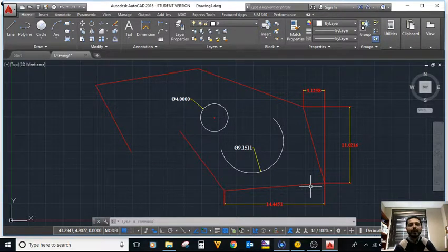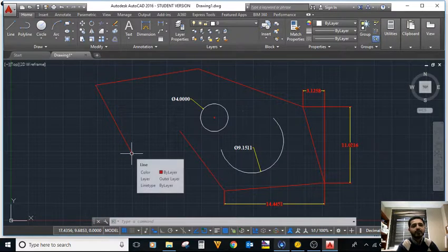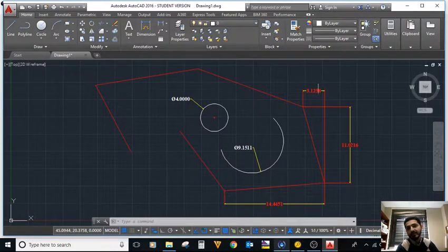Okay. How about if you don't like the style of the linear dimension like this, you might be interested to know what's the dimension of the exact length of this element. I'm not interested in the vertical distance between this point and this point, neither the horizontal distance. I'm interested in the aligned dimension, which is the true length of that element. So yes, there is an option in AutoCAD. So let's do this.